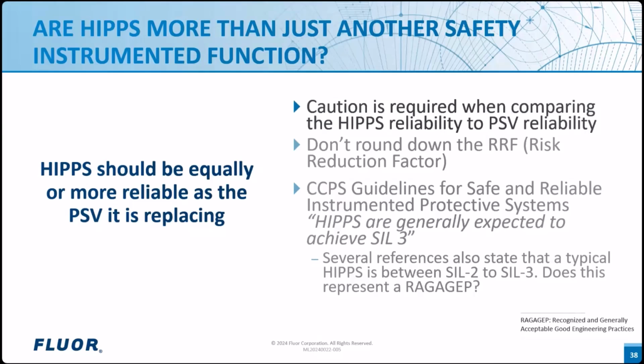It depends on the valve type and the service. For the purpose of LOPA, the reliability of a PSV might be conservatively low to ensure additional safeguards are provided during the LOPA. However, this is not conservative when using this basis for comparison as to the target the HIPPS should satisfy. In some cases, a HIPPS is being used because the PSV is inherently unreliable in the given service. Making the argument that the HIPPS only needs to be as reliable as an unreliable PSV is not very convincing.